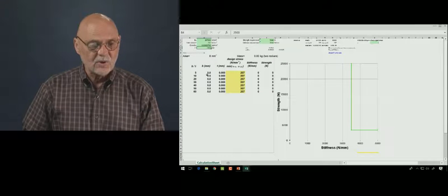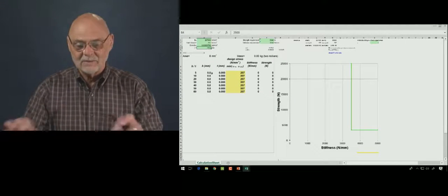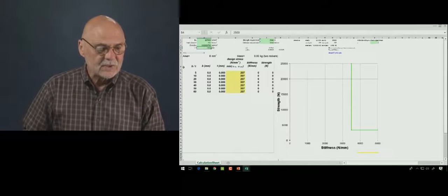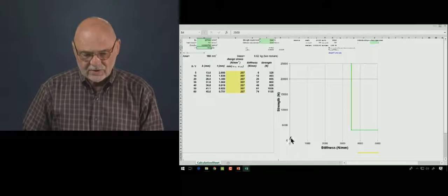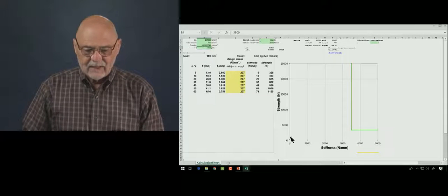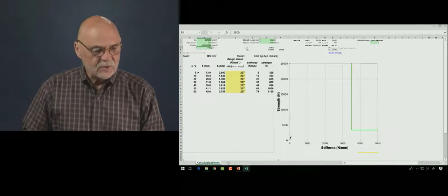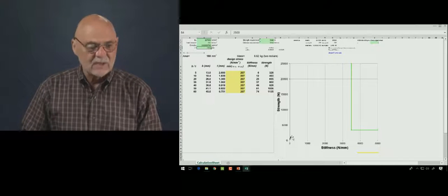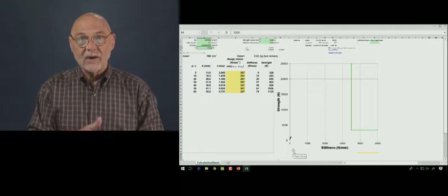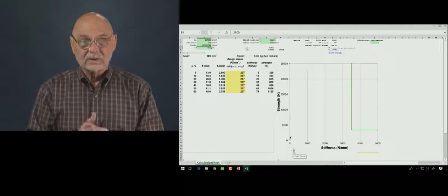I have zero area, so we have essentially no beam right now. So let's just add some cross-sectional area here. Okay. So what you see on the chart here is a little worm, and we have 2, 4, 6, 7 different solutions here, 7 different beams from a B over T ratio of 5 all the way up to 60.